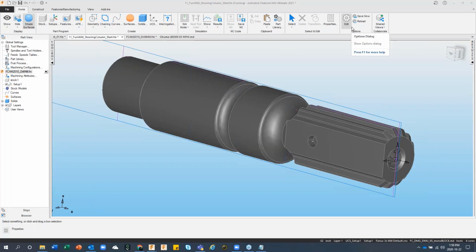So the machine basically has a main spindle, subspindle. It has a 5-axis milling head up top and a regular lathe turret with Y on the bottom. So when I started programming this, a lot of what I was doing was by hand, and all this synchronization magic that you guys are seeing here today, I used to have to do all that manually. Okay, a lot of the tool paths that I would use, I would create manually, literally at the controller on a keyboard, punching numbers and working that way.